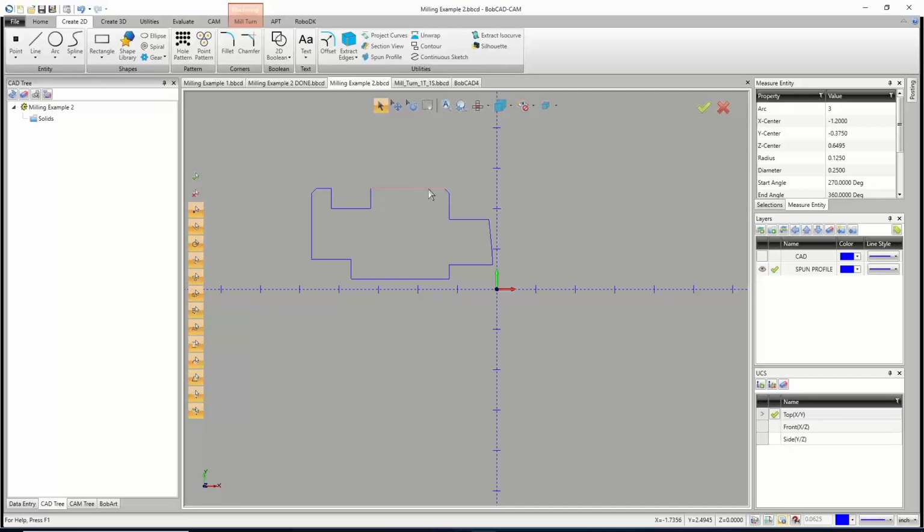So when we hold shift and click on something, if you're right in the middle, you won't really know which way to go. So don't click right in the middle. Click at like the 3/4 point, 3/4 of the way down this way or 3/4 of the way down this way. Whichever side is the long side is the direction that we're going to send the chain.